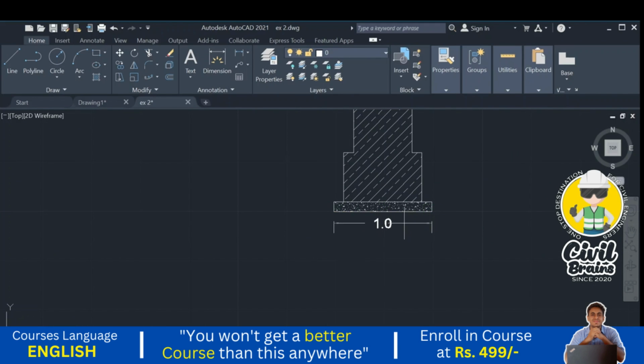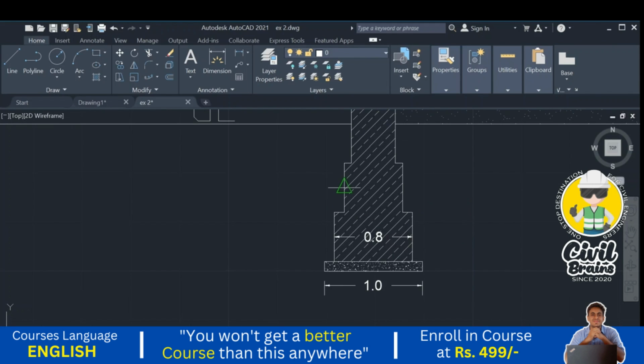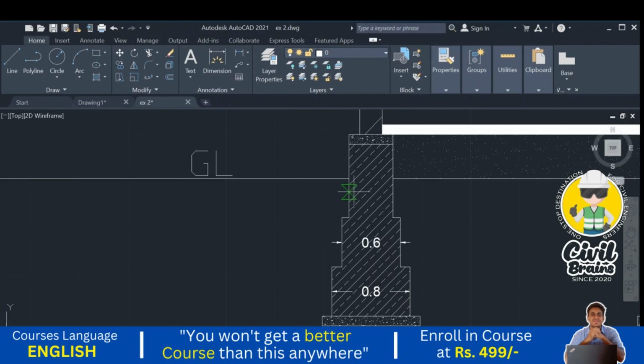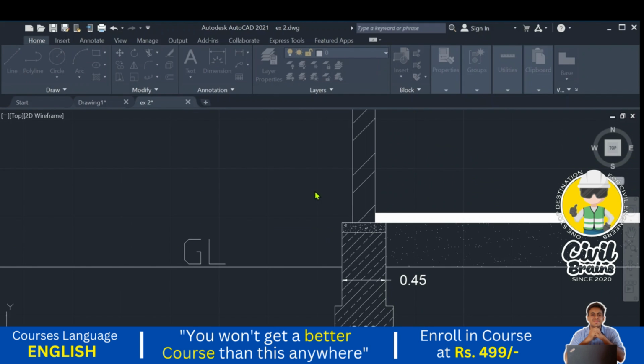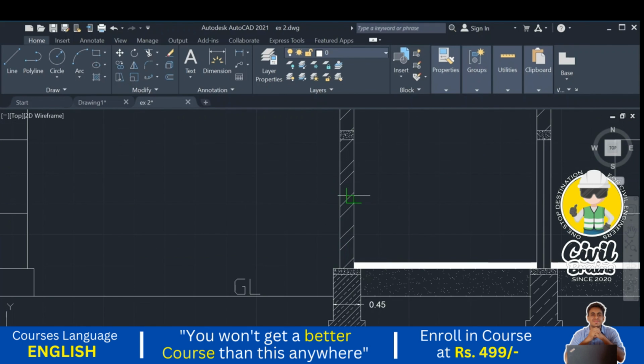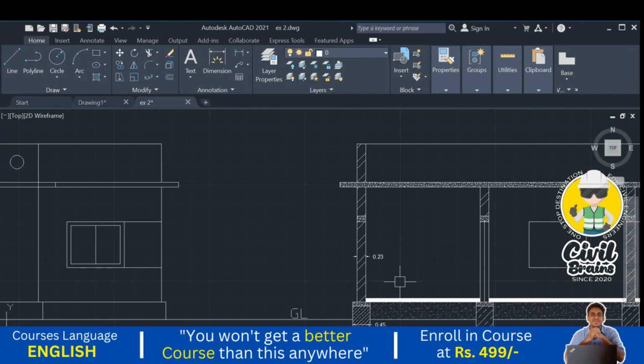width of the PCC, next width of the first step, width of the second step, width of the plinth, it is 0.45. I just change these fractions. Once you change the fraction, you will get it. Next, width of the wall, okay, 1 second.